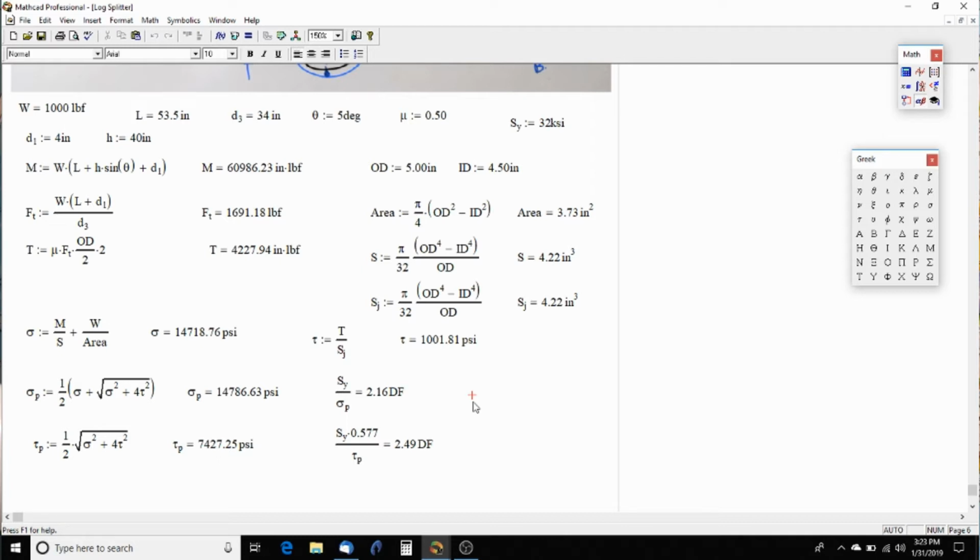So either we need to go back and look at using a bigger tube, maybe taking a material sample of the tube, or just do a hardness test on a non-critical part, and that can give you a better idea of what the yield strength actually is. So in this case, 32 ksi is rather low. But if we moved it up to 40 ksi, or if it was a DOM tubing of, I believe 60 ksi is 1020 DOM, or you can get up to 72 with a 1026 DOM tubing. So you can look in there. I think we'll just keep it there for now.